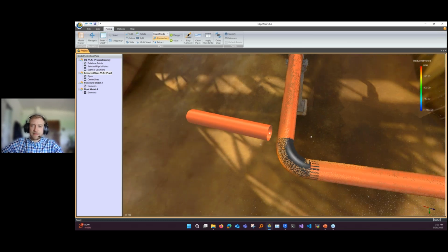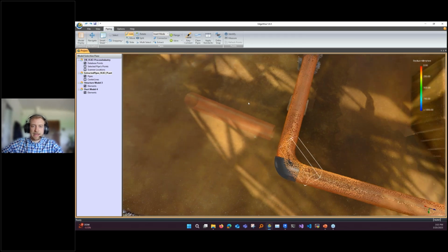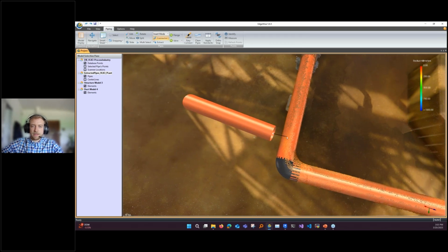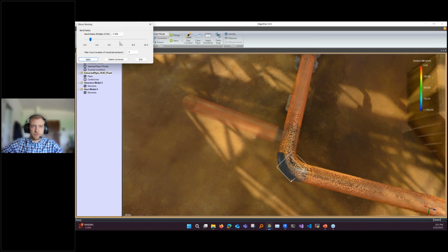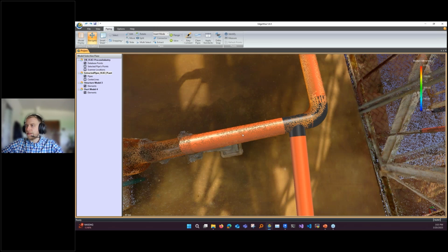The way you can get around that is you can go to the edit function, edit the elbow bend radius, and make it tiny. You can then add your T in, and then go back to your elbow radius and put it back-ish. It's probably better to not let it overlap too much, but that can be super nice. That's a good one to get around.